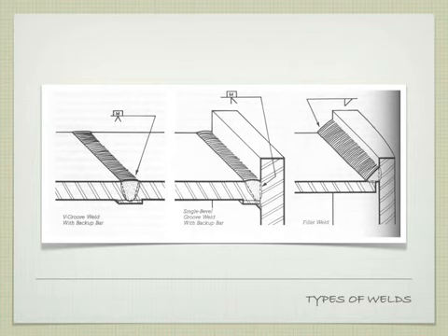If we get to the side here, right, same configuration, horizontal piece and a vertical piece, right? We're doing what's called a fillet weld, okay? So we're heating up and melting this side. We're heating up and melting the top bit of this surface, right? And we're making our weld in between at the joint. Notice, however, it's not a full penetration weld because it doesn't go all the way through this piece, right? This becomes a much weaker joint than this would be, right?